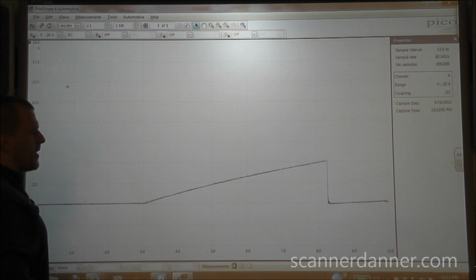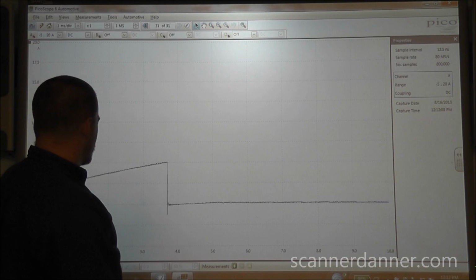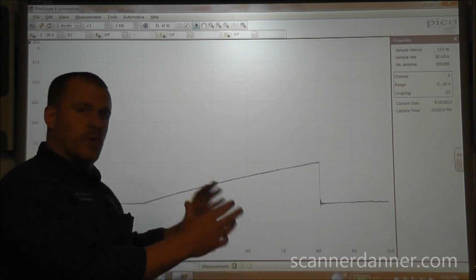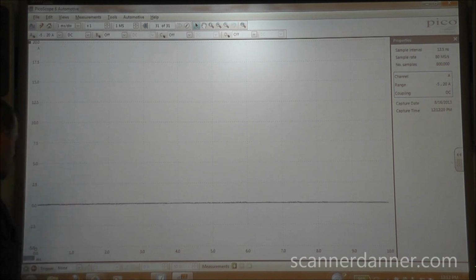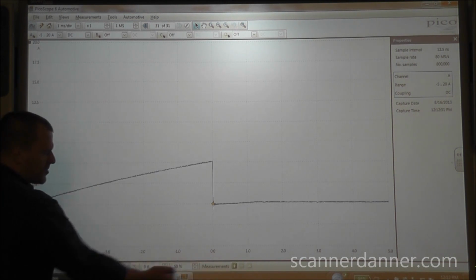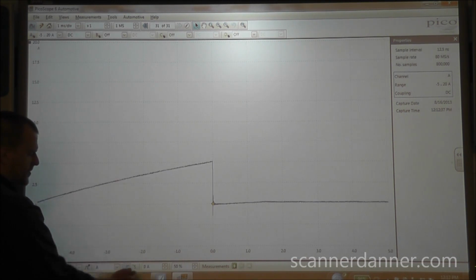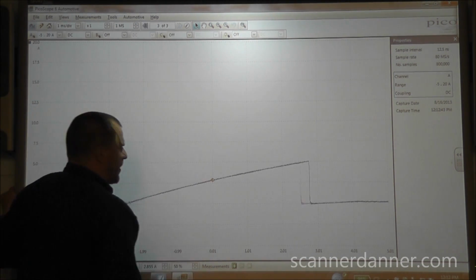And I think what you're seeing right now is we have a problem. And the problem is that signal is rolling off of the screen. And what if we want to see detail of the signal and we want it to stay still? This would be an example of when you'd want to set a trigger. And so I'm going to do that. Down here on trigger, I'm going to select repeat. And this little dot here on the screen is my trigger point. This is telling me some information about that trigger point. It is 50% delayed. It's set at 0 amps on a rising direction, and I want to cover these with you guys. I'm going to pull this up out of that.